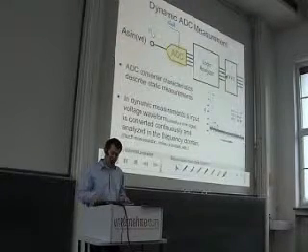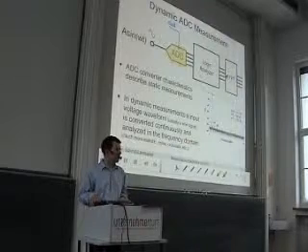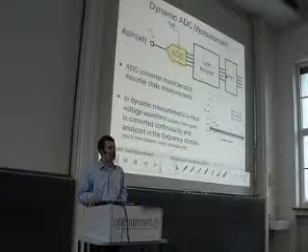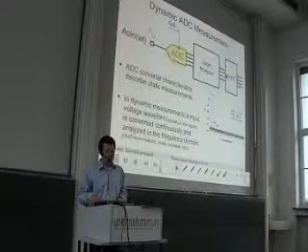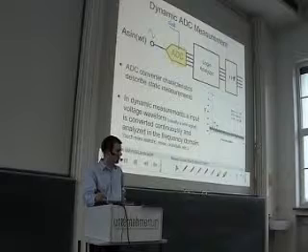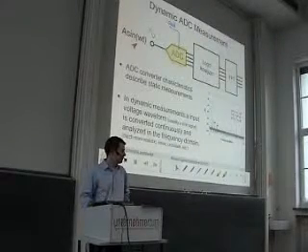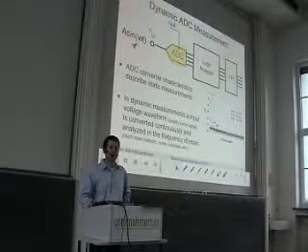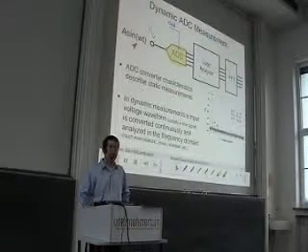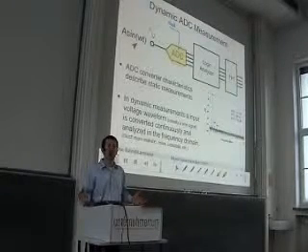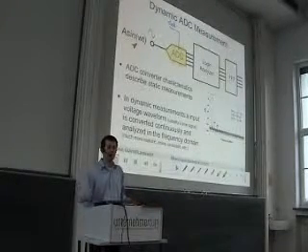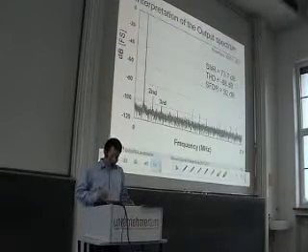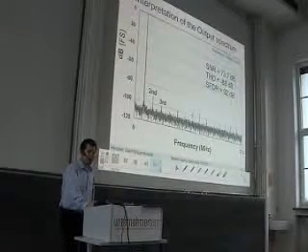So my question for you is, here you have already a small plot of this. What will you expect in the ideal case that is coming out of your FFT? Here we have a sine, and we convert this for a while with our converter. Yes, so we would expect that there are two Diracs, okay? One at a positive frequency, one at a negative frequency. If we look at the result, it usually looks like this.